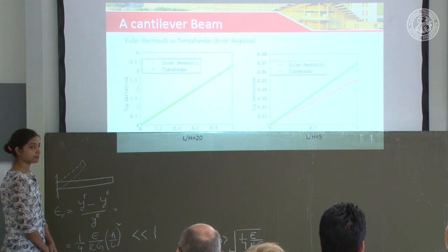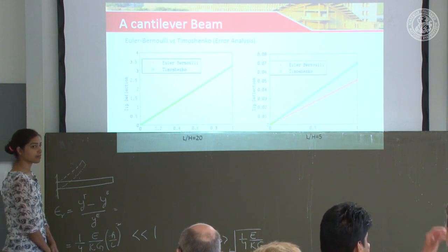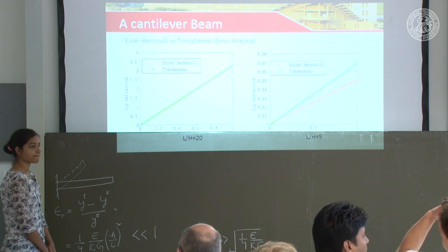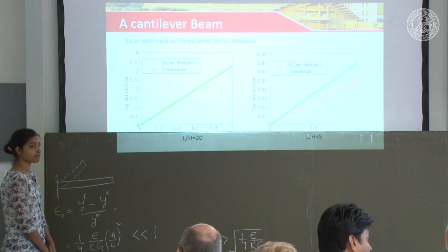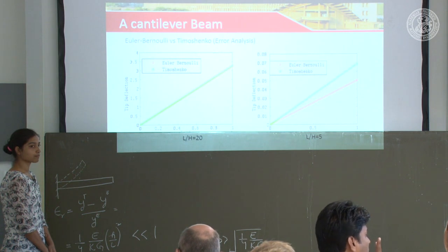No, that does not come here because this is for planar deflection. So we have to first think of which plane the beam is deflecting in. And then we only take the moment of area of that particular plane. No, again, we don't take the ratio of the moment of area.